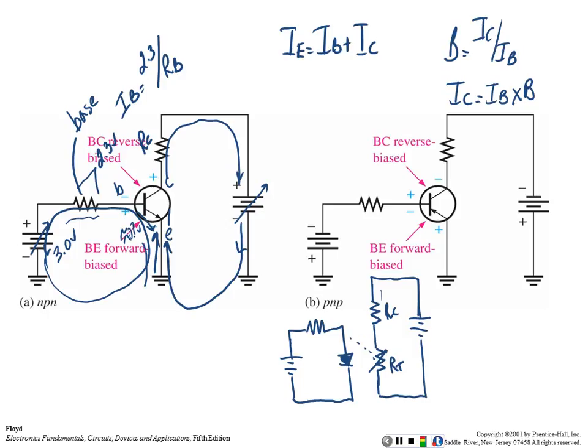What I'm trying to let you know is that what happens over on the collector side, the collector-emitter side, is controlled by what's happening on the base side, right? You understand? So we're using base current to control the opening and closing of the valve, and it works just like a water valve. We can cut it off, or we can turn it wide open, or we can operate it between cut off and all the way on, and we call that the active region.